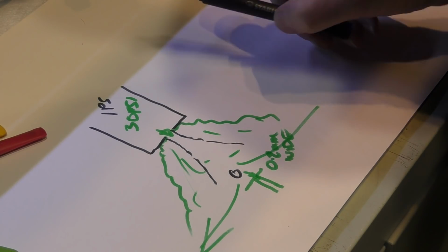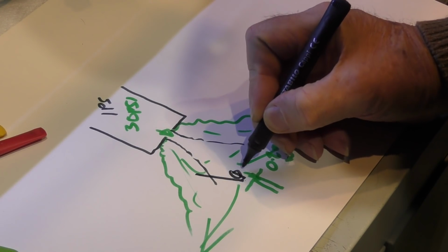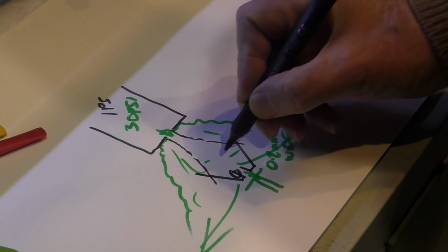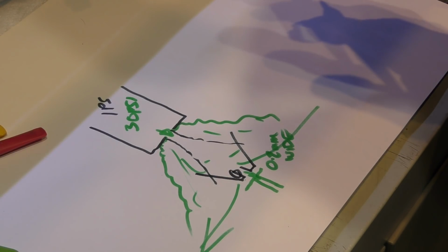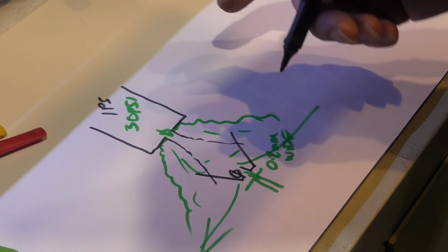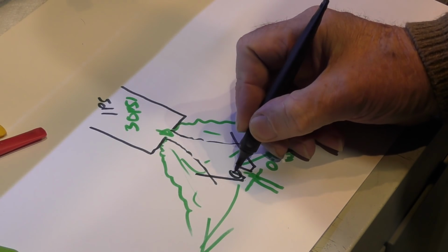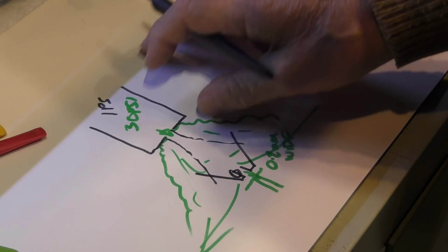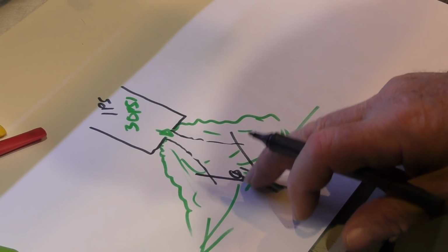The right approach is to try and get a nozzle with a small orifice like this and get it as close as possible to the work. And you don't need high pressure, as I've demonstrated to you. 2-3 psi, even pulsing 2-3 psi. But because what happens is this pulsing action that's taking place with this pump is being met with this restriction here. So what we've got basically is like an accumulator in the system. The system is actually damping out the pulses when we've got a restriction right at the end of the system.